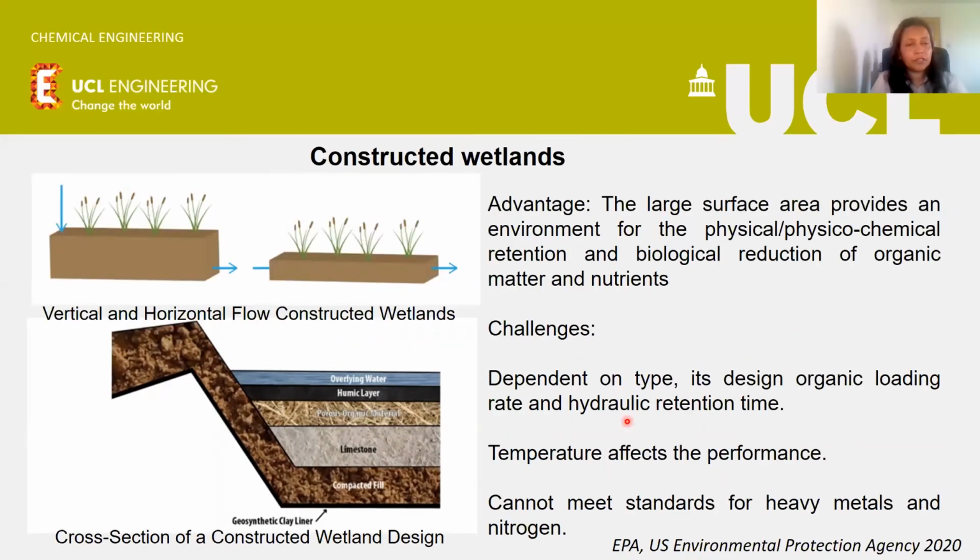There is an advantage, obviously, because it's mimicking a natural situation. There's a large surface area where wetlands can be created, and it can help in the physical and chemical retention and biological reduction of organic matter and nutrients. That's a big, big advantage. But there is a challenge because temperature affects the performance. It works very well in cold countries, but not in all places of the world.